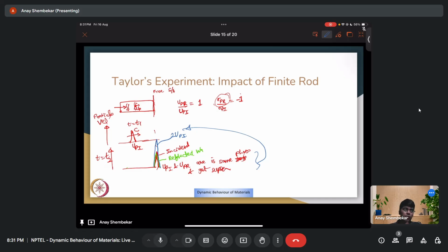Part of my PhD problem is on wave propagation in structures. When we do an analysis like this, if you hit a rod with some velocity and take a very low impedance material on the right hand side, which mimics the free surface effects, then very close to the free surface, if you look at the particle velocity, it becomes roughly twice as much as your initial particle velocity.